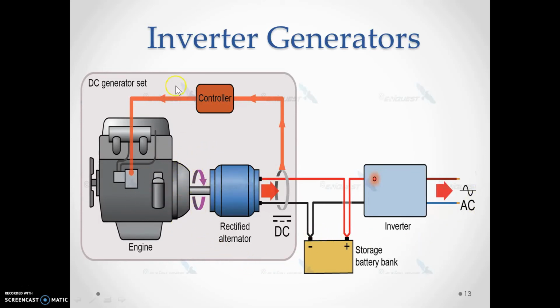As the engine increases in speed, the DC voltage rises, but as the load increases, the voltage will fall. The microprocessor controlling the inverter compensates by sensing the AC output voltage of the generator and adjusting the speed to keep the voltage at a consistent level. This saves fuel since the engine only turns as fast as necessary instead of at a constant high speed, creating wastage. As the demand increases, the microprocessor speeds up the engine and power production increases.